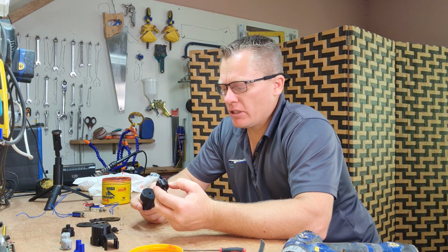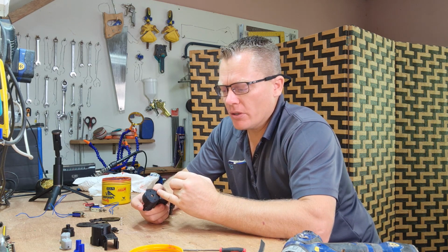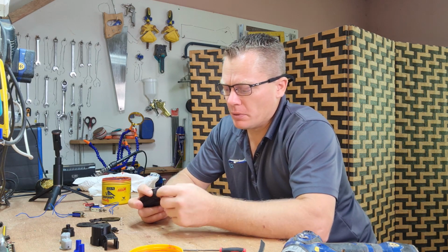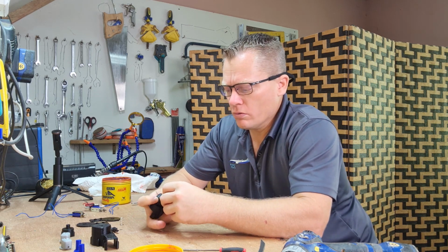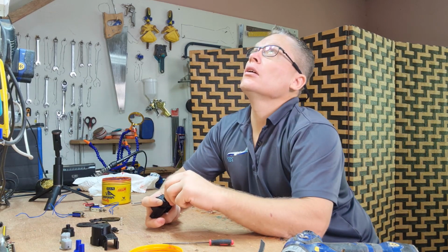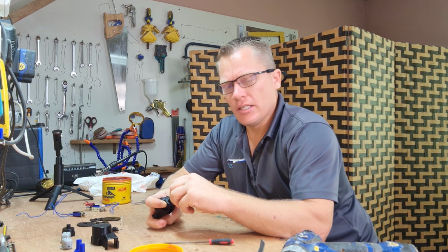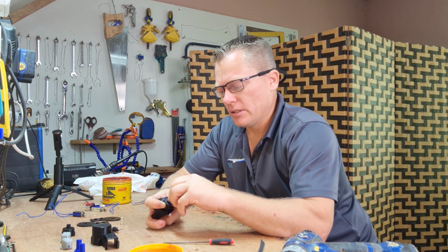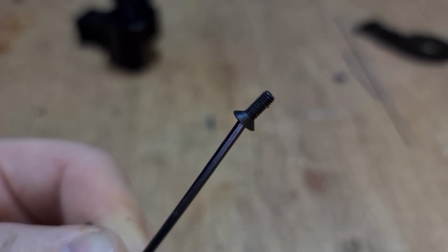We've got our two parts ready to be assembled, but first of all we need to check the fit. We've got a hole in our lower body and we've got a spigot on our upper body. Push the two parts together, compress the spring, align the hole and the spigot here and here, and then just push it in and feel for nice easy operation. And that's feeling quite good. You can see here that I'm using flathead screws, but you can quite easily use dome head as well.